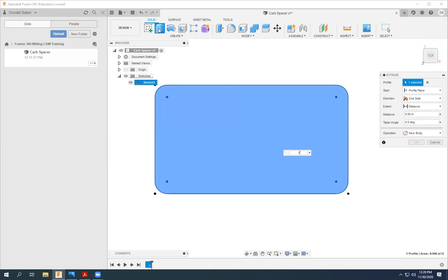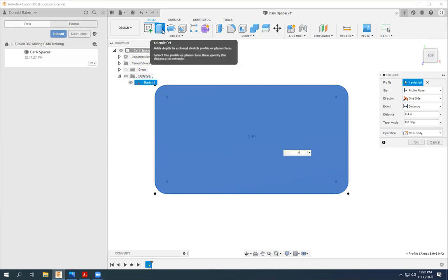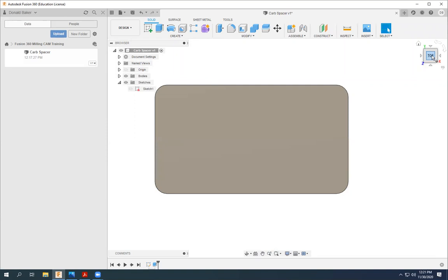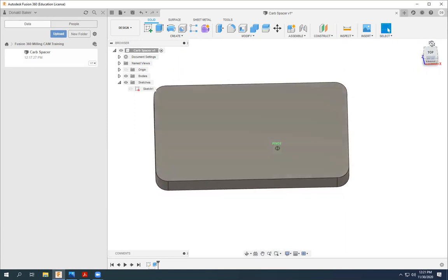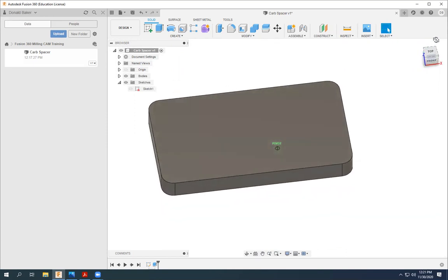So go ahead and put the height of the part, which is 400 thousandths, just by clicking into the blue sketch and then entering 400 thousandths and then clicking OK. Now, if I go back to my navigation tool at the top and then start to rotate that, I can see my part pivot and rotate in space. So I can see that that third dimension's been created.